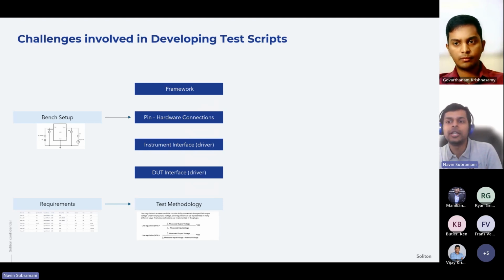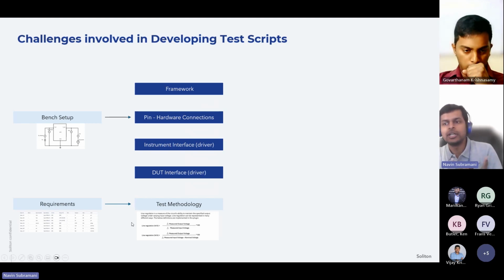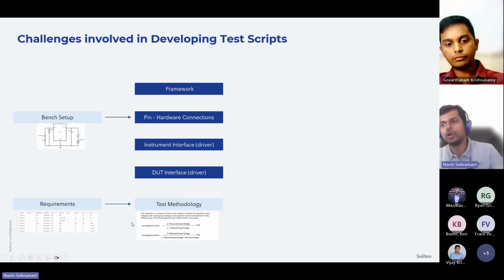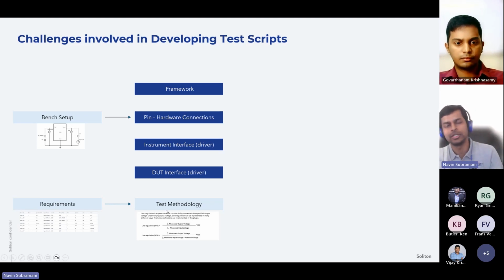Each company and organization has its own test procedures for doing certain measurements more efficiently for their data. So this is something the engineer comes up with based on tribal knowledge within their company or field. For a line regulation, they might set the load current constant, then vary the input voltage and measure the output voltage. Here is a formula, this is how I make a measurement. You write that particular test methodology.